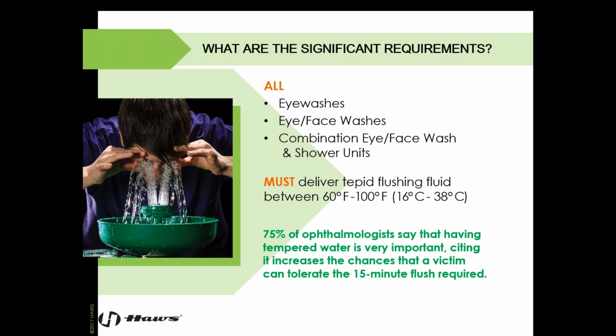All eyewashes, eye face washes, combination eye face washes, and shower units need to deliver tepid flushing fluid. This one, as we mentioned, was a revision that was added in the 2009 standard. It was also in the standard prior to that, but there were no temperature parameters defined. So in 2009, they actually put a minimum and a maximum temperature range, which is 60 degrees Fahrenheit to 100 degrees Fahrenheit. A key piece to remember is that the equipment isn't considered compliant at the time of purchase, but rather at the installation and post-testing.